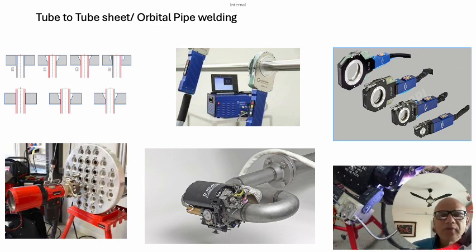And when you have very sensitive tubes, like in the case of semiconductors or food and beverages, you cannot have a penetration, so you need to control your internal purging pressure, as well as use closed loop or closed system orbital welders or open system orbital welders. What I have shown here are all closed type systems where there is no separate ceramic, but the torch is only